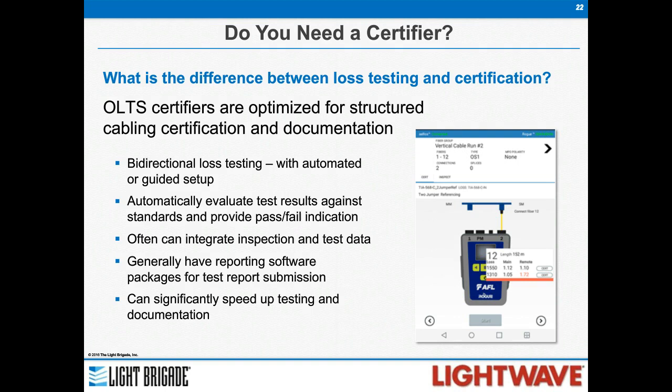If you have to meet a certain standard, maybe you're testing to TIA 568C, you want automatic pass-fail, so you don't have to record everything and do your calculations or keep a long chart. These pieces of equipment will do auto pass-fail. They'll track if you tested and you failed, and then you maybe cleaned your connectors again and you passed. You'll see that history. So they give you a lot of great data. So I wouldn't call this a best practice necessarily. It's not required, but this is something that can be very helpful in documentation and testing.